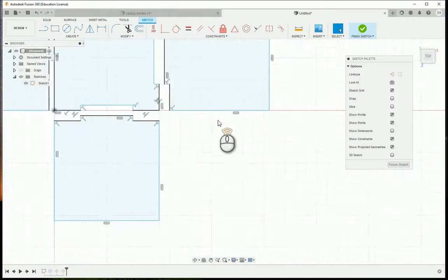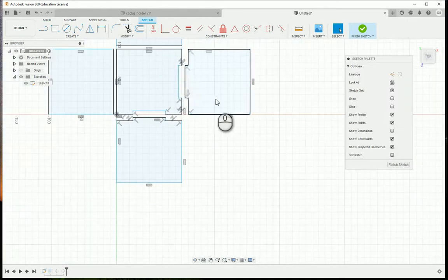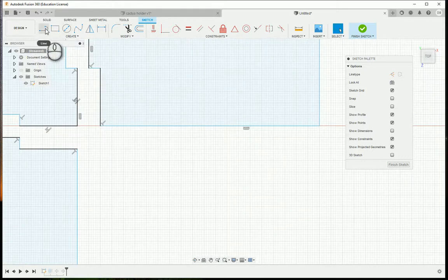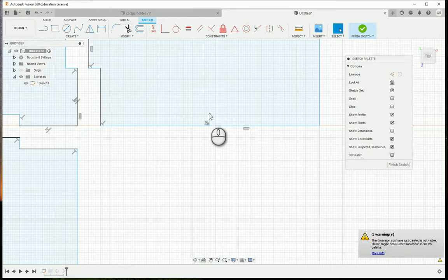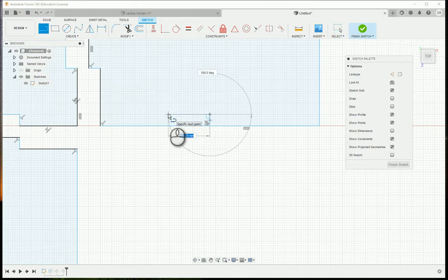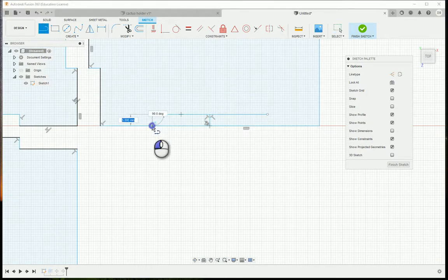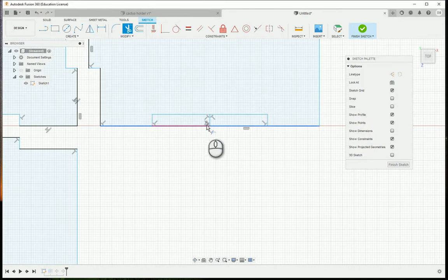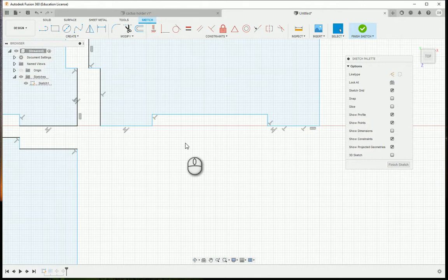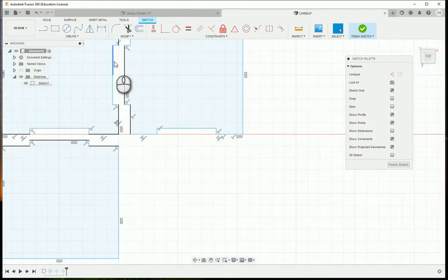So let's start by taking out the middle bit. That's nice and easy. It's exactly the same as you've just done here, and all I need to do is again slide along here to the middle, go in 5, use the line tool, 25, line, 25. And then I can come down off of here, come down off of there, and I can trim that middle bit out that I don't need. Pretty much exactly the same as this.